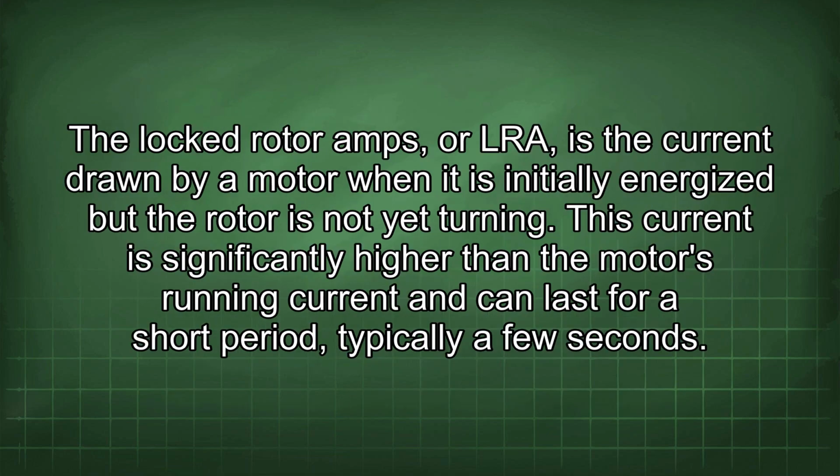The locked rotor amps, or LRA, is the current drawn by a motor when it is initially energized but the rotor is not yet turning. This current is significantly higher than the motor's running current and can last for a short period, typically a few seconds.